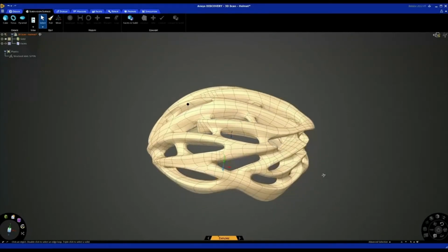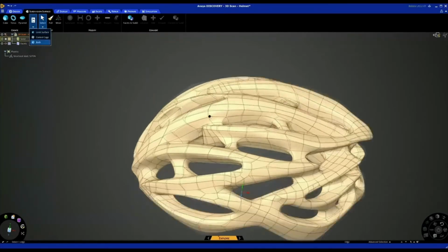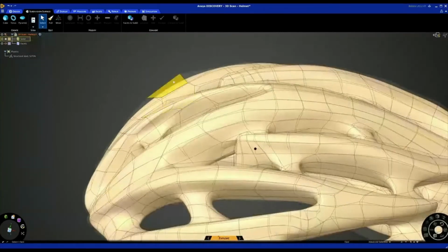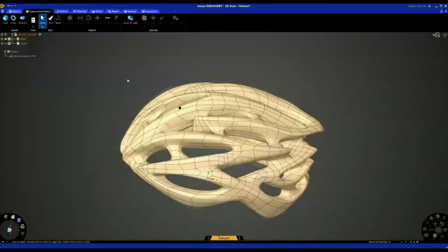So what it's done is it's converted the facets, it's subdivided it into a number of surfaces, and in the sub-D surfacing tab we're able to modify technically the cage code, which allows us to actually modify the geometry. Just to view that cage, the cage that we're actually modifying, we just view both, and we can sort of see this behind the surfacing, and that's obviously what you modify, and by doing that the surfaces change. I like to just turn that off.